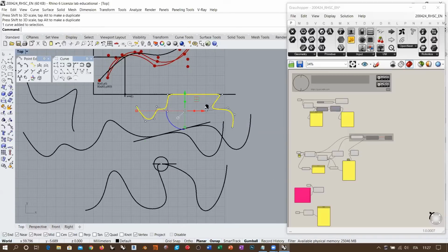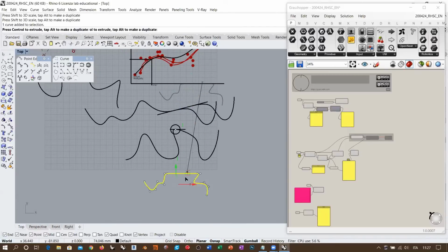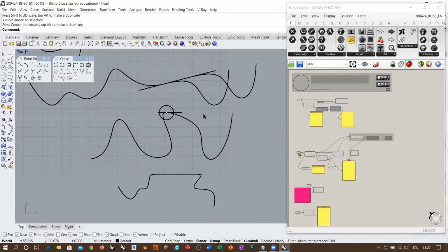Okay, now all that we are saying here, these are what I call the three basic rules for NURBS curve definition. So initial and final tangency, passage through a point or tangency along an internal point of our NURBS curve, and flat portion of a NURBS curve. With these rules, you can basically create whatever type of condition that you might want to create.